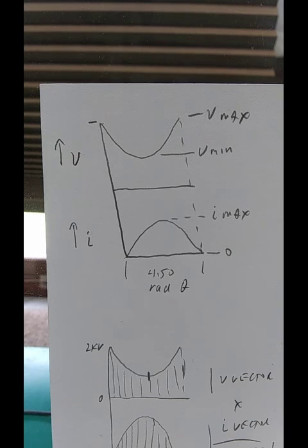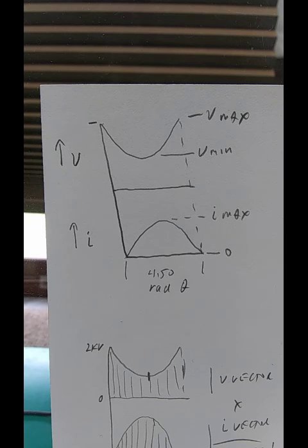Two-part graph. Top portion is plate voltage curve. Bottom is plate current. As previously, the plate current's easy to integrate. Take the maximum times 0.637. That gives the average. Can't do that with the plate voltage on top because the plate voltage is not referenced to the zero line. Integration finds the area under the curve, not over it. And what we need in this case is, for the voltage, we need the area over the curve, and we've got to find that by other means.